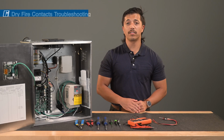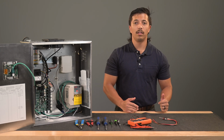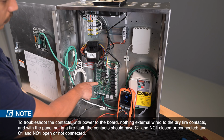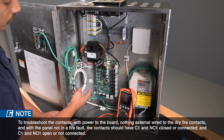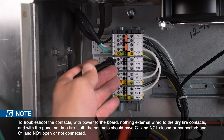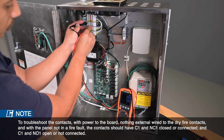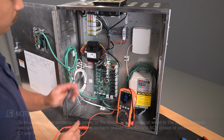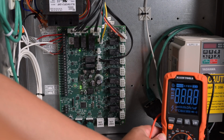The best way to test the dry fire contacts is to troubleshoot the relay on the board. To troubleshoot the contacts with power to the board, nothing external wired to the dry fire contacts, and with the panel not in a fire fault, the contacts should have C1 and NC1 closed or connected. C1 and NO1 should be open or not connected. You could test this with a voltmeter set on the continuity setting.